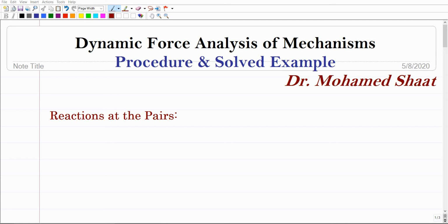Just a quick reminder of the things that we already covered in the previous video. We gave a little bit of an introduction about this topic and what it means, what the difference is between static force analysis and dynamic force analysis. Also, we discussed different important cases that we would experience when we consider the force analysis of different mechanisms. Like the case where we may have a member or a link that is subjected to two forces at the ends. We give it a name: two force member. Also, we discussed how we can do force analysis for a three force member.